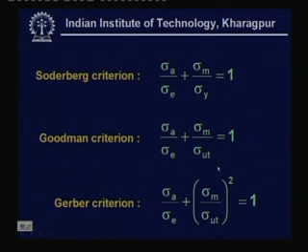And the last equation, sigma A by sigma endurance plus sigma m by sigma ultimate whole squared equals 1, is called the Gerber parabolic relationship. Out of these 3 equations one can utilize any one to go for the design